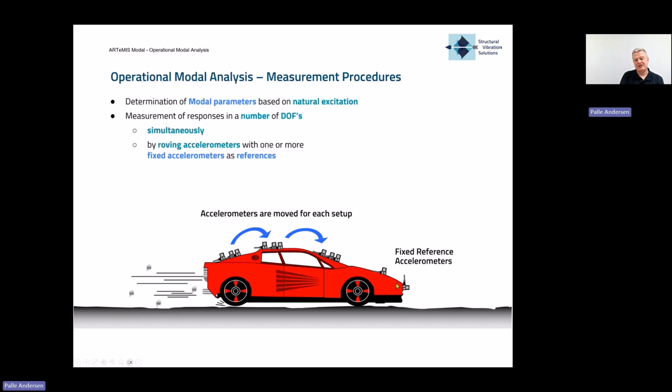If you look at it, absolutely, the level of vibration changes. But we have, you could say, the shape of these two here, so we have to end up having similar information for all 3 measurements that have been done in these 2 locations here. And then we use some least squares technique to estimate the relation between one measurement and the next one and the next one again, so that we end up having a parameter that we can multiply the different parts with, so that they end up with the same level. And we then get a global mode shape in the end that looks good.